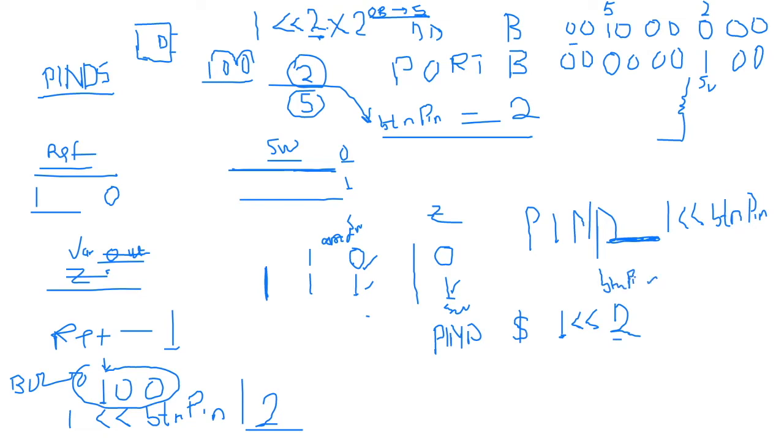So what I'm saying is, I'm picking pin D, which is here, and I'm saying, okay, I have a 1. At the moment, I set all this to 0 by using the bitwise shifting, and I have a 1 here. Then I perform an AND with it. My style of writing AND changes all the time. I perform an AND with it, so I get the actual state of that pin. Because if it is a 0, I get a 0. If it is a 1, I get a 1.